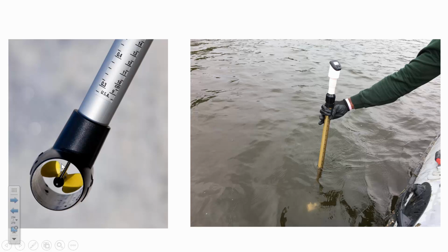You know, there's going to be some drag, and so they probably have correction factors that are built into the instrument on the top of the tube, where they know that if you have 1 meter per second going through this opening, then probably the surrounding water is flowing at maybe 1.1 meters per second. So they figured that all out in the lab. And now what they can do is take this into the field and measure the flow rate by knowing the flow velocity at any point, and then integrating that over the width of the channel.